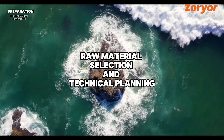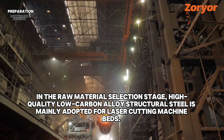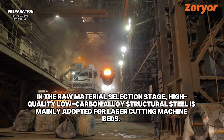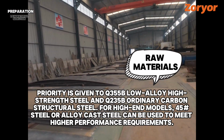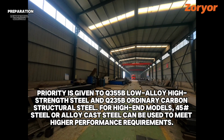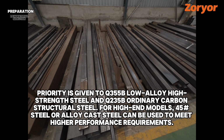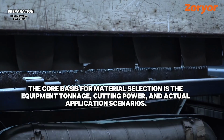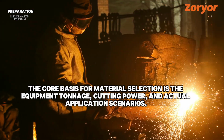Preparation stage: raw material selection and technical planning. In the raw material selection stage, high-quality, low-carbon alloy structural steel is mainly adopted for laser cutting machine beds. Priority is given to Q355B low-alloy high-strength steel and Q235B ordinary carbon structural steel. For high-end models, 45 steel or alloy cast steel can be used to meet higher performance requirements. The core basis for material selection is the equipment tonnage, cutting power, and actual application scenarios.